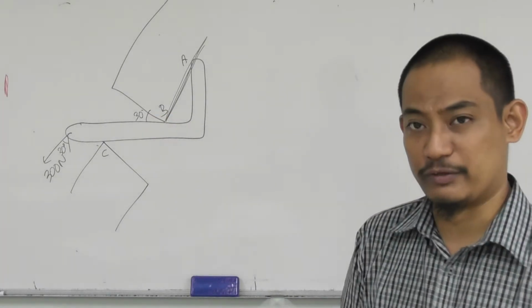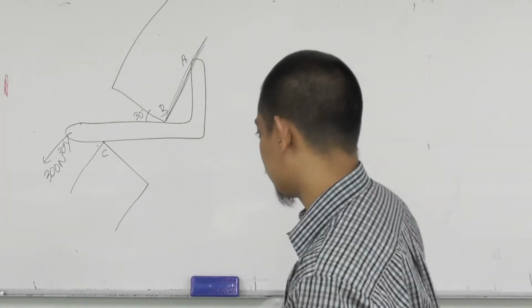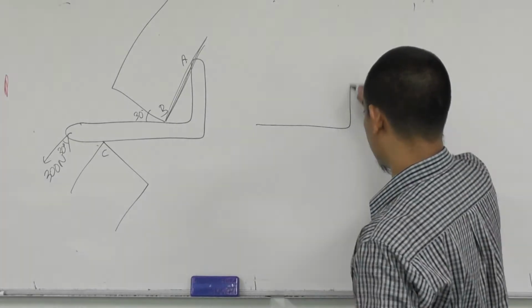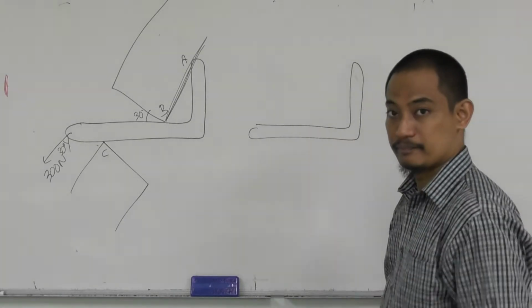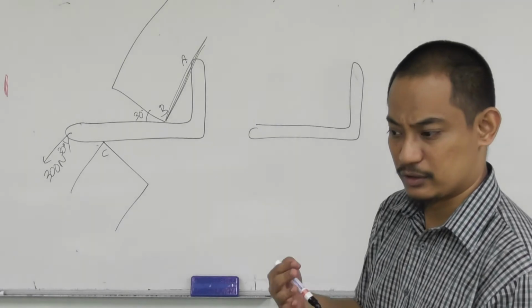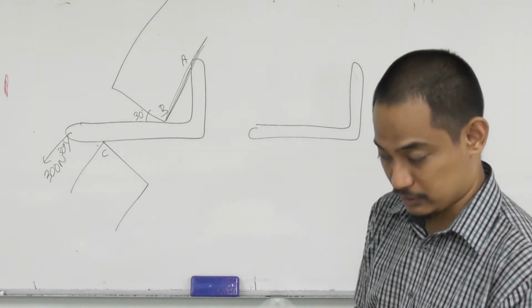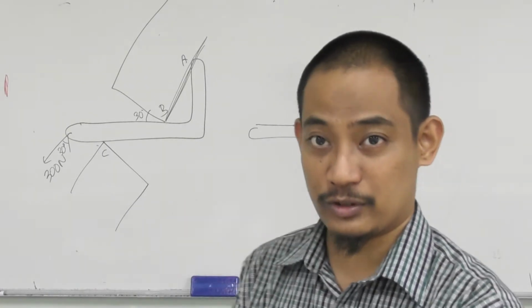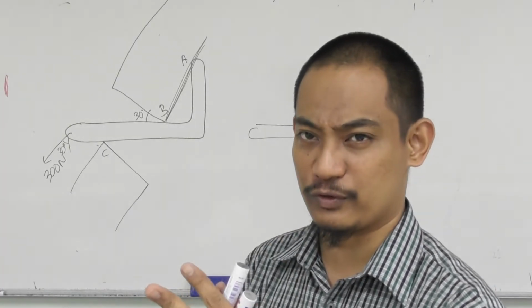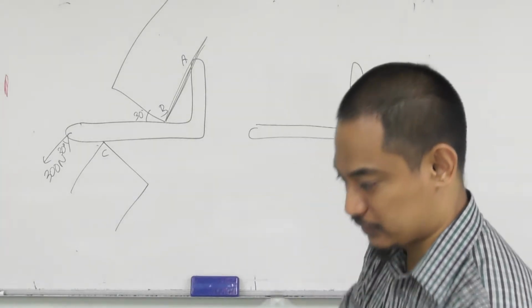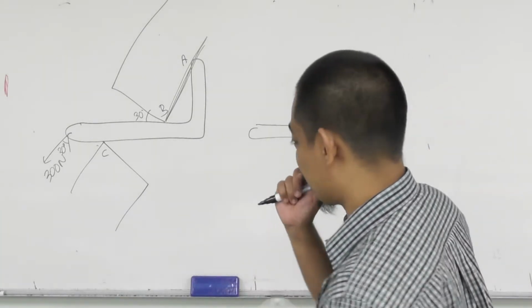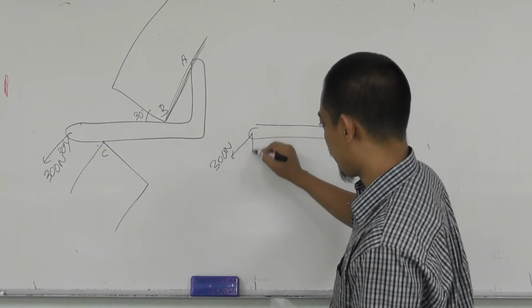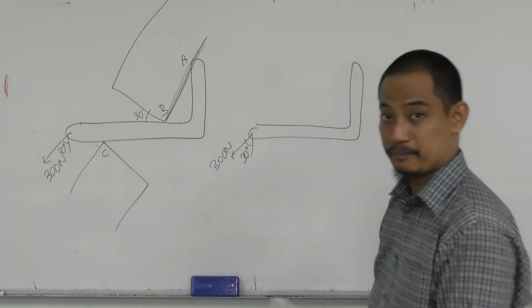So if you have to draw the free body diagram, the first step is again to draw the outline of the shape of this. So it's something like this, right? And then you draw the forces. The dimensions, of course. Just a reminder, I do not show all the dimensions because I assume it's straightforward for you, you can draw it. I'm just focusing on the support direction and the forces direction. So you have here 300 Newton at 30 degrees there.